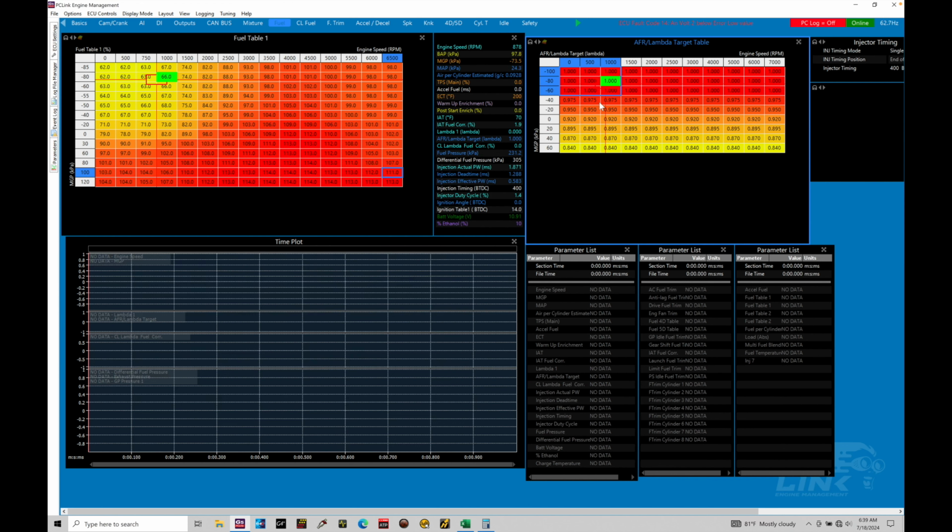This gives us an improvement in our engine stability, as well as giving a little bit more engine torque output out of the engine. When we fire up an engine, there's going to be frictional losses for a cold engine. Engine hasn't warmed up yet, so the engine's going to want to idle a little bit lower. We can offset some of that lost torque output from frictional losses on a cold engine by running a little bit richer target lambda target air fuel mixture.